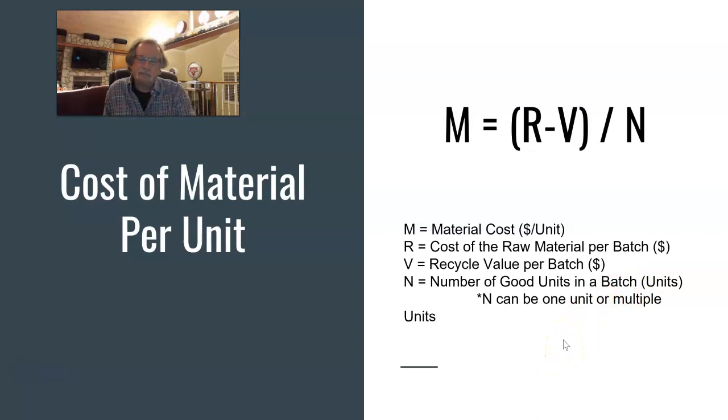Okay, now, when we're looking at this, don't just rely on this formula by itself. You need to apply some common sense to it. So if, for example, when calculating N, we know that something is 72 inches long and it needs to be machined into 8-inch pieces, that would tell you that you could have 9 pieces.